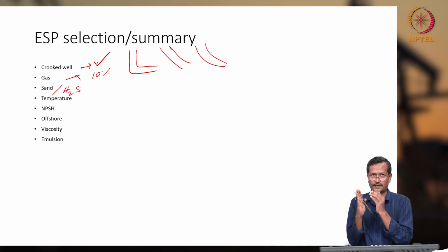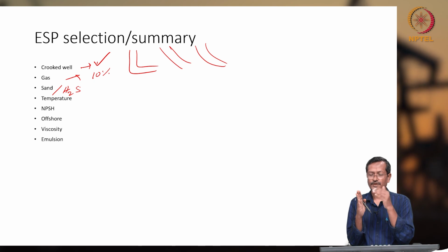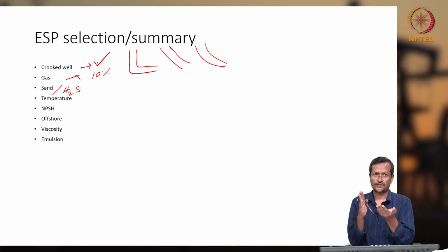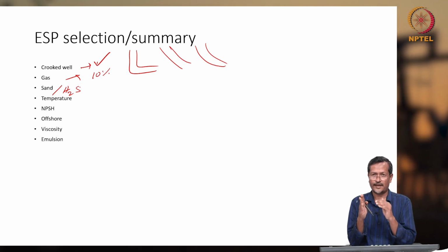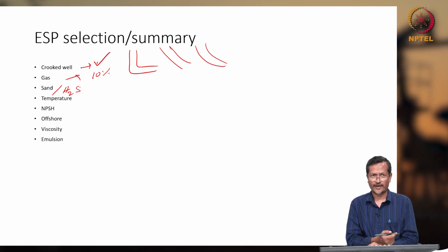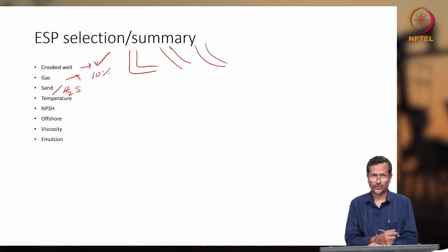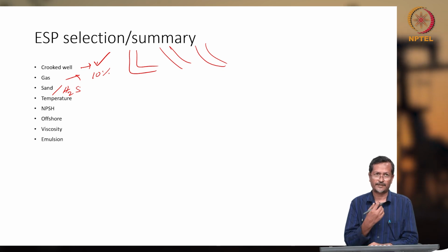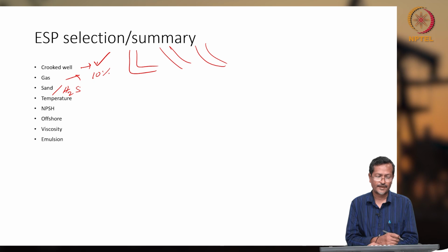And what will happen? Metal will be reacting again with hydrogen sulfide, again sand will hit, it will remove. So erosion and corrosion both will work together and metal will be degrading quickly. Okay, and at the same time you have cavitation issue also. Again there will be erosion, corrosion and cavitation all together, a more complex situation.